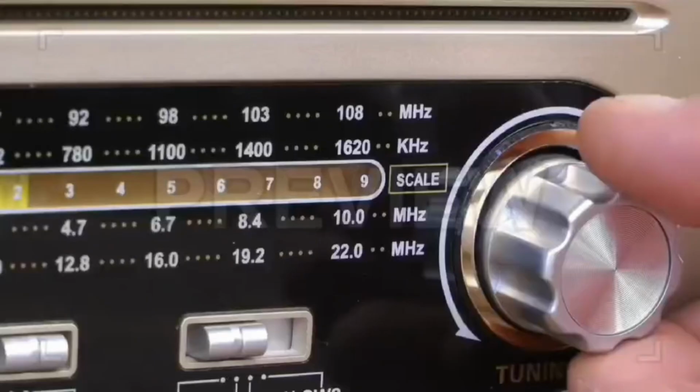This is resonance. The resonant frequency is just F0 equals 1/2 pi times the square root of L times C. When turning this dial, we are literally tuning this circuit to match the broadcast frequency of a radio station, maximizing the current and pulling that signal out of the air.